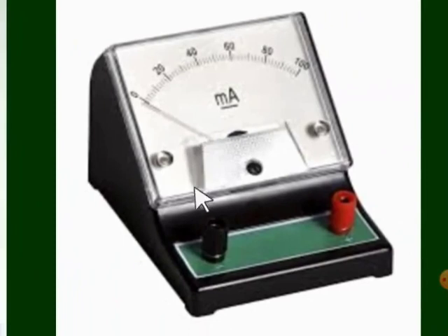And for the milliammeter, here you will see the black terminal and the red terminal. The black is meant for negative. That means you have to connect the negative terminal of the battery or the circuit here and the positive terminal onto the red terminal. Here you will also see the scale, written as small mA. That means the current here is to be measured in terms of milliampere, okay? And you will see here 0, 20, 40 like that, up to 100. So this milliammeter can read up to 100 milliampere. Got it?